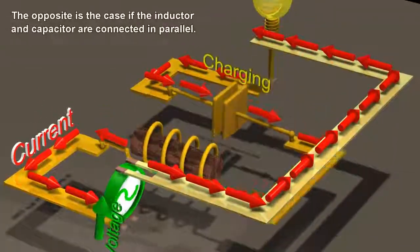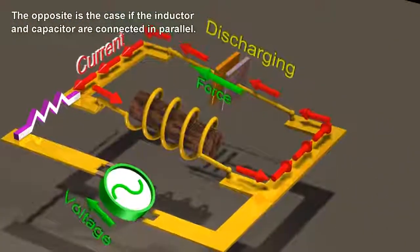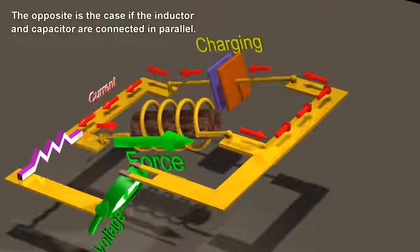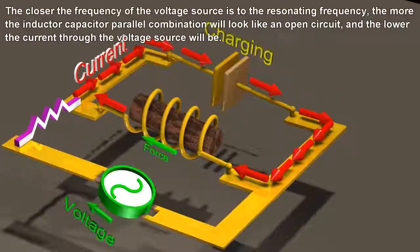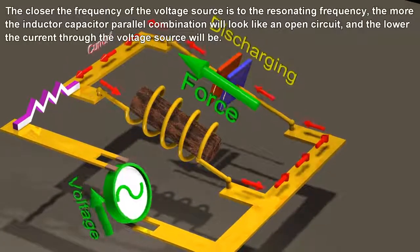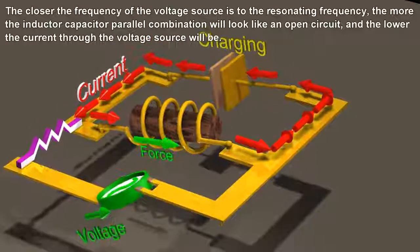The opposite is the case if the inductor and capacitor are connected in parallel. The closer the frequency of the voltage source is to the resonating frequency, the more the inductor-capacitor parallel combination will look like an open circuit, and the lower the current through the voltage source will be.